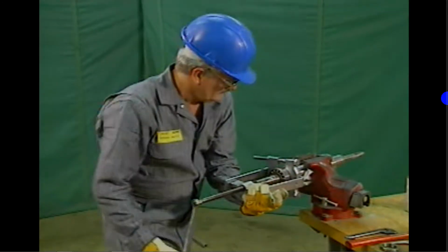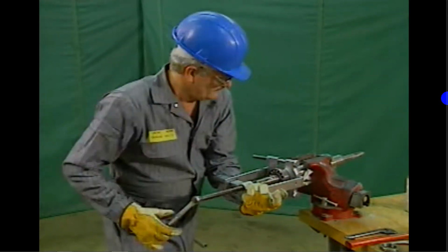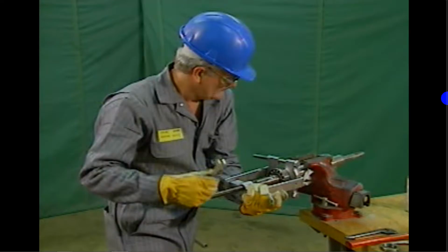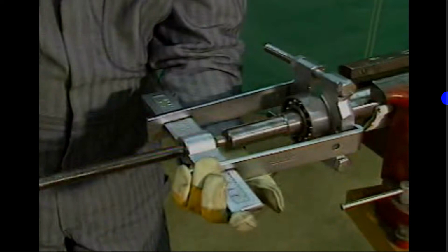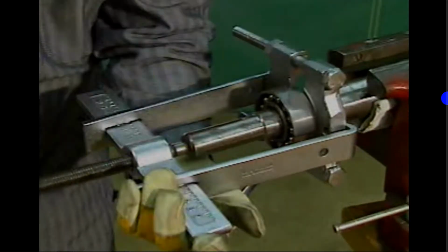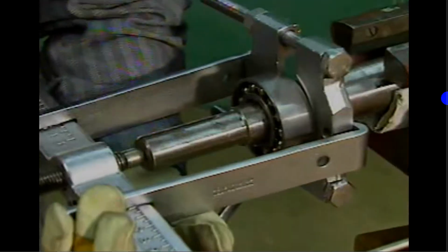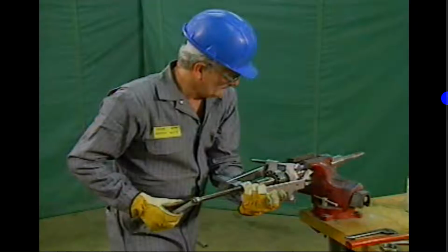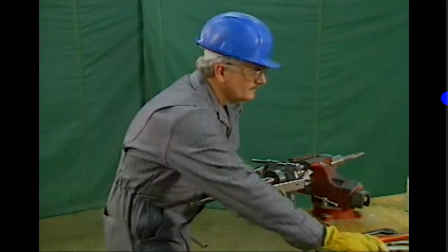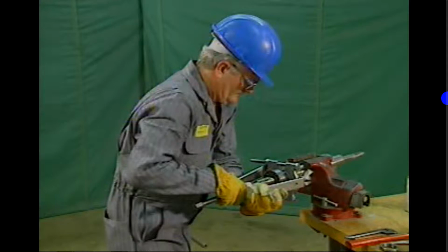The mechanic begins by carefully removing and cleaning the damaged bearing. After a bearing has been removed from a shaft, it should be handled carefully. It should not be left where it will get dirtier, and it should not be rotated, banged around, or dropped. Handling the bearing carelessly will only make the task of determining why it failed more difficult.